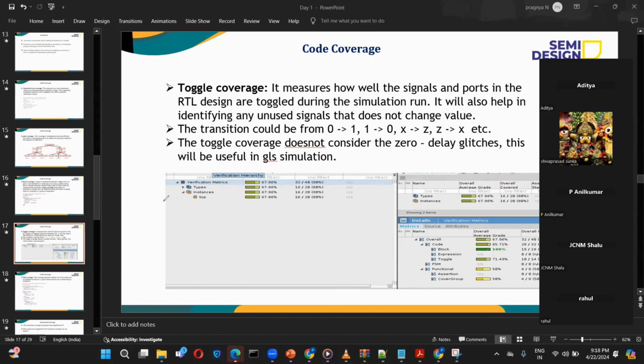How will it be generated? We can just write A of 0, A of 1, up to A of 15. Is it okay with that? Basically, you will just declare the variable and turn on the code coverage in the simulator. The code coverage simulator will give us this report, right?